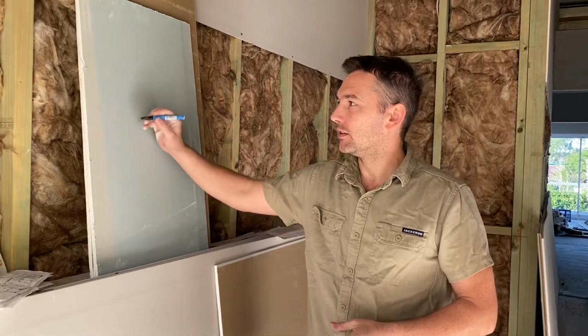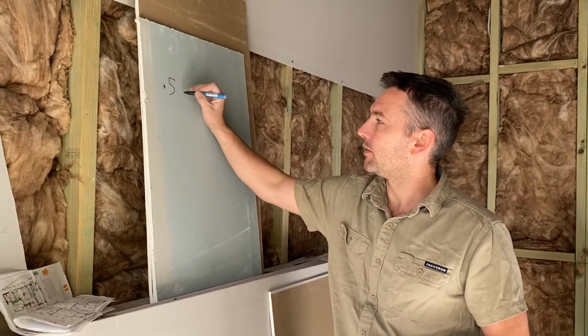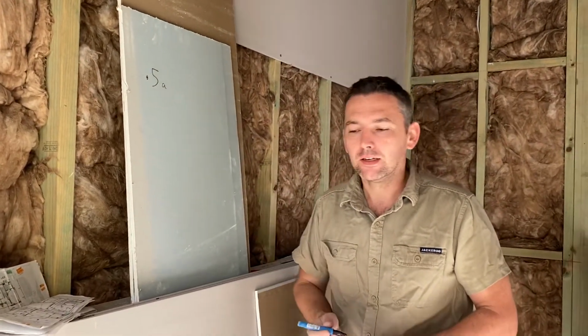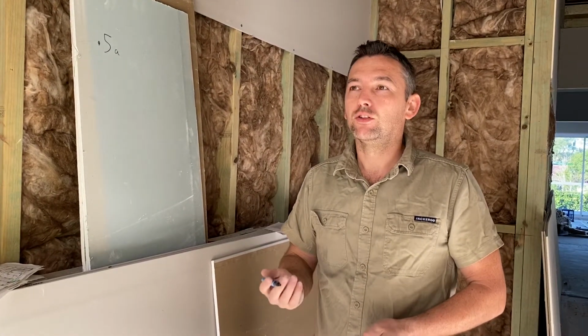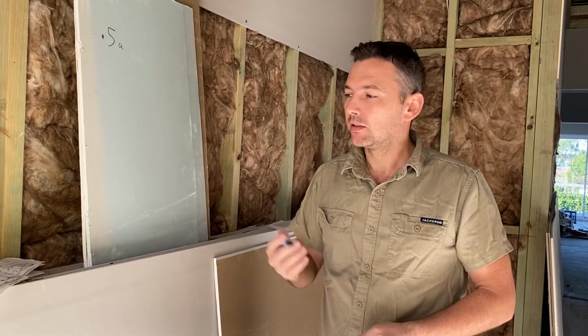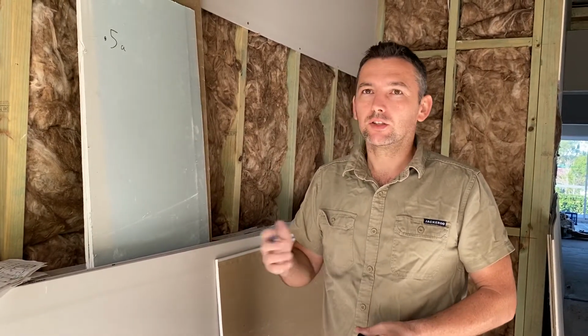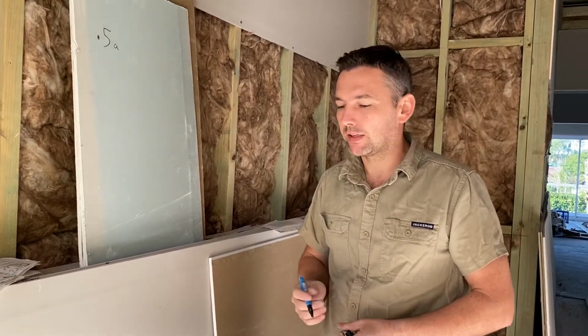Okay, we're going to talk about how to plan your lighting circuits. So the AS3000 2018, the guidelines I'm using here in Australia, gives a guidance of 0.5 amps per light fitting. Now it's a guidance. Lights today with LEDs do draw a lot less power. It's a good idea to use the guidance though, just in case someone switches out the light to something else.